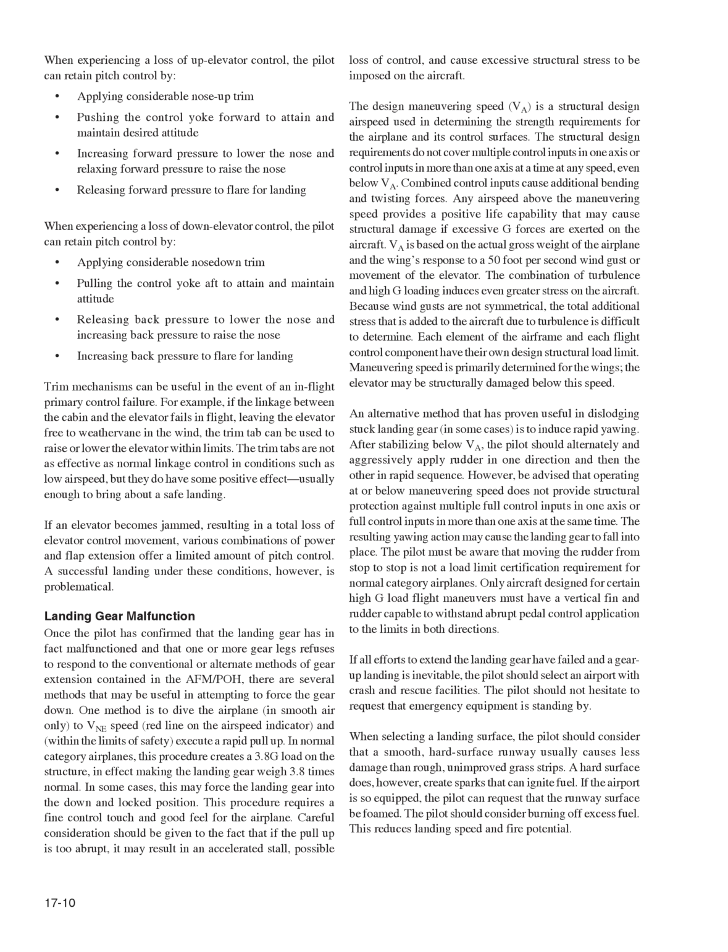The pilot must be aware that moving the rudder from stop to stop is not a load limit certification requirement for normal category airplanes. Only aircraft designed for certain high G-load flight maneuvers must have a vertical fin and rudder capable to withstand abrupt pedal control application to the limits in both directions.